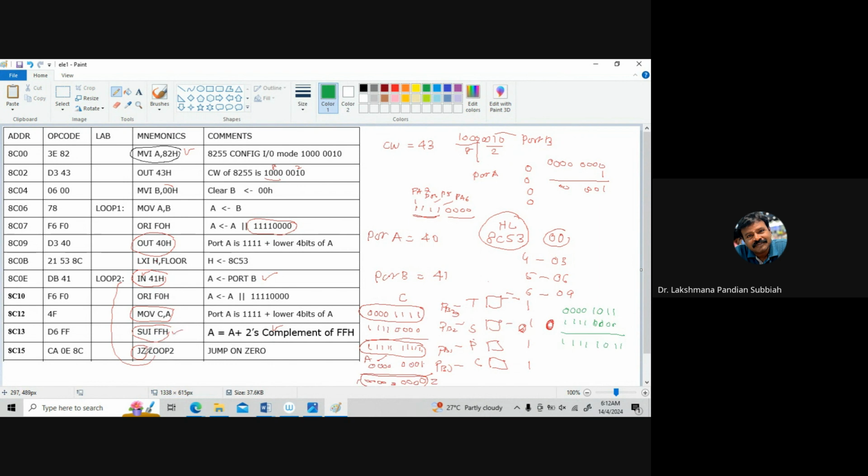Now you see this, the 0 flag. So if you are doing that, it is not 0, right? So here we are having subtract immediate with F0. What will you get now? Some value you will get, right? If you are subtracting that value with this one, so this one is the complement, then we are getting this 0 0 0 1, right? So we are getting some value, it's not 0. Then this condition is not satisfied, then it will come down to the next one, right? So 0 is not there, you are pressing some key, so the 0 flag is not set.